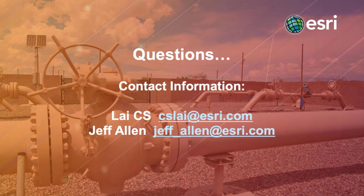And so the way that we've modeled this is we have the larger pipe segments in the utility network, and we're modeling the pipe lengths as individual ranged events on top of that pipe with those welds in between. So if I ever wanted to get back to, say, a heat number or a joint number, I can simply query that pipe segment linear event or pipe length linear event, and then dynamically segment that back with my pipe in the utility network to get the characteristics. So we're modeling pipes as lengths, larger pipes as utility network objects, and then welds on top of that.